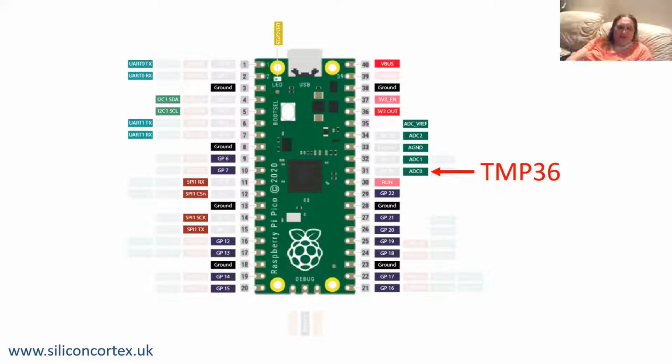Stephen, yes. I've just looked up the ADC value. The ADC value might be 16-bit, but the actual ADC physically is only 12-bit, which is why your bottom 4 bits are not so great. Yeah, you see, so the last 4 bits. But I wouldn't ever trust the bottom 4 bits anyway.